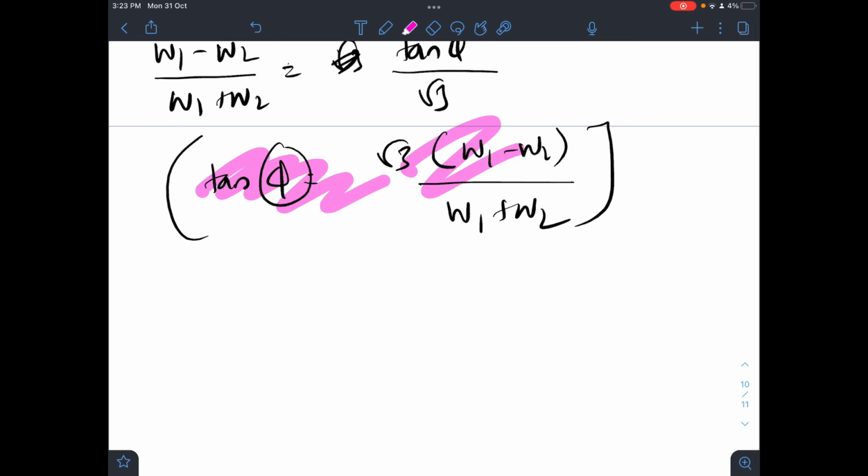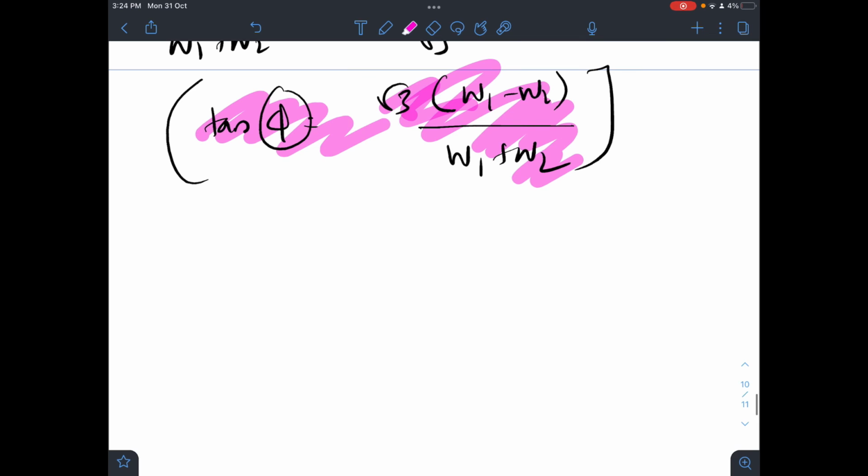This equation is important, and you should also understand that you can measure 3-phase power using the 2 wattmeter method. Instead of this, you can also try using 3 wattmeters placed on each of the phases with respect to neutral, and add all these up in order to get the 3-phase power. That is not an issue. So that also you can do. No problems with that. But we can use a 2 wattmeter method even in a 3-phase 3-wire connection to have the 3-phase power measurement.